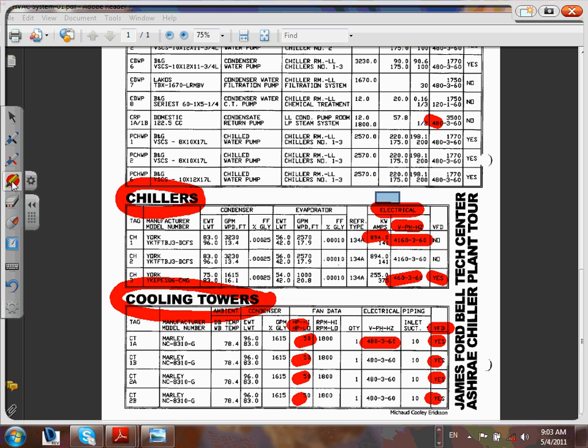The top ones, the pumps, are also motors. Done. We did motors. So we did all the work for these two. And guess what the chillers are? The AC system, cooling system. Did we do that, guys, for the AC system? Yes. I gave you a calculation. And we remember that locked rotor current and so forth, and we size it by 1.25 times the full load current of the chiller, and you size the overcurrent protection device for a chiller, guys. What we said, 2.25 or 1.75, depending how we're going to do it, and you go down.